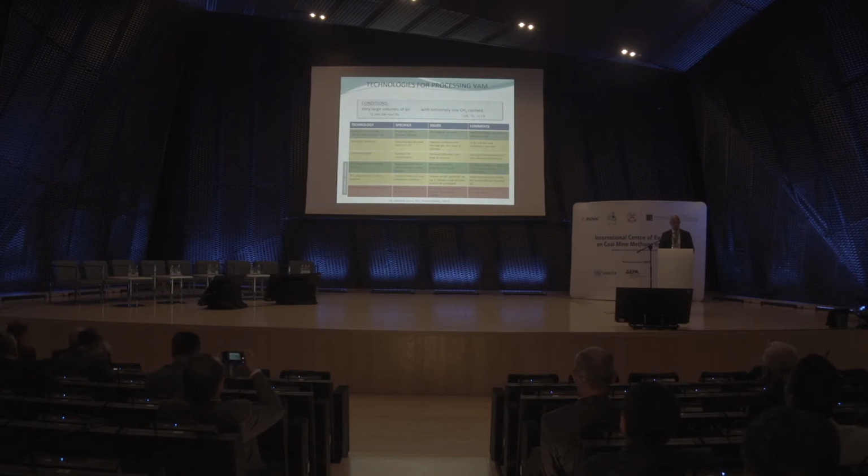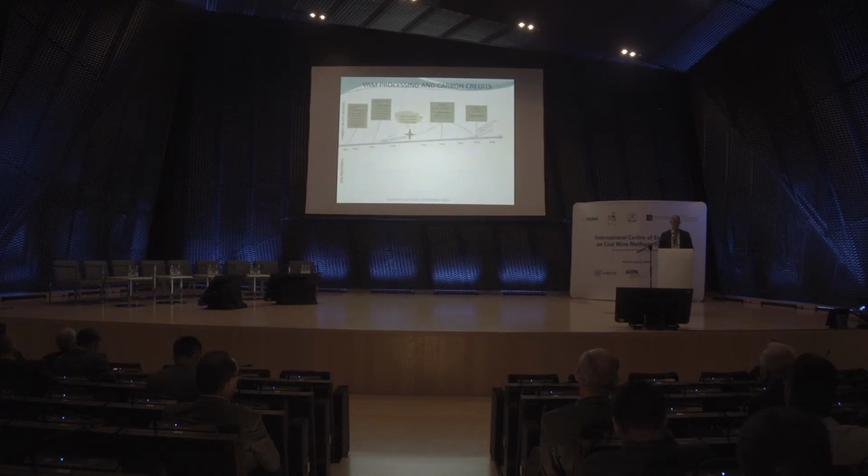Regenerative catalytic can be interesting, but the catalyst is often sensitive, and you can poison the catalyst, and at some point you need to replace it. So at this point in time, regenerative thermal oxidizers are the most interesting proven technology.